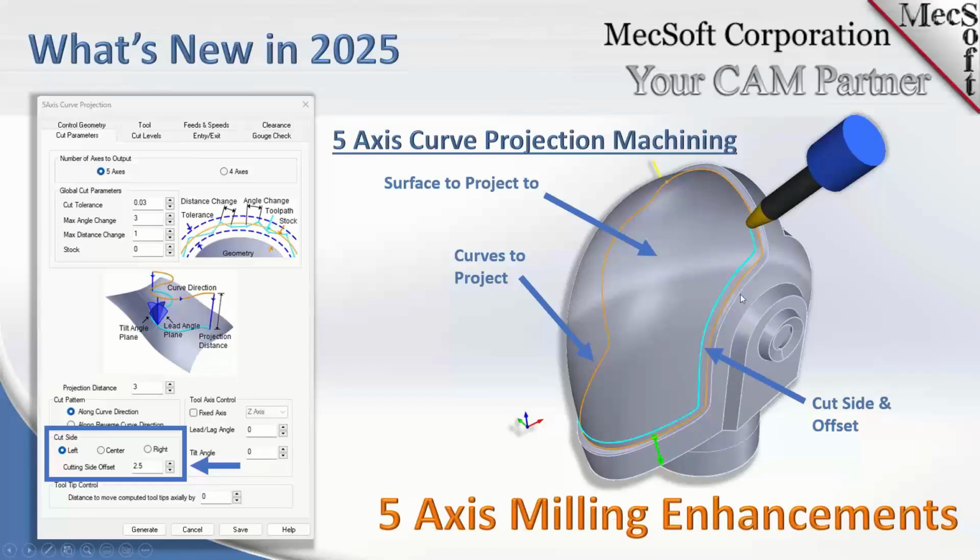And if you look at this edge in orange, you'll see that it's at the base of a raised area. So prior, in 2024, if you wanted to add curve machining in this area, there's a chance that it would ride up on this vertical face as it goes around this complex area. So if that occurred, then obviously you would want to use another method to try to clear up these areas.